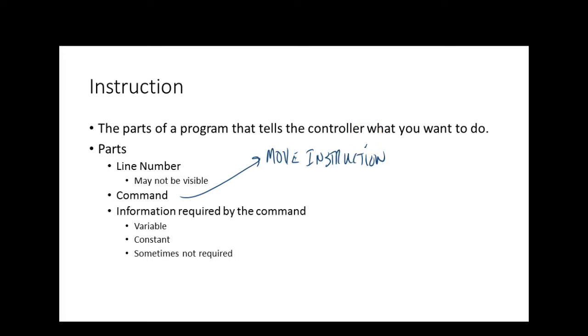Of course, these instructions are going to tell the robot how we want it to move. We'll look at these, but there are basically three on all these robots. We have what we call a joint move, a linear move, and a circular move. Some robots support more, none of them support less. We'll find that anything we want this robot to do, we can do with these three moves, which is pretty neat. If we had to do tons of moves, it would be hard, but with these three, programming or teaching the robot is a lot easier.